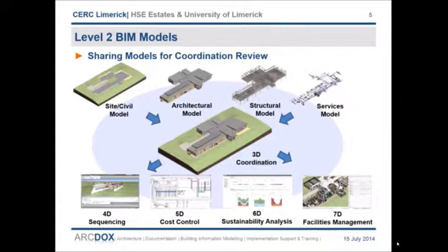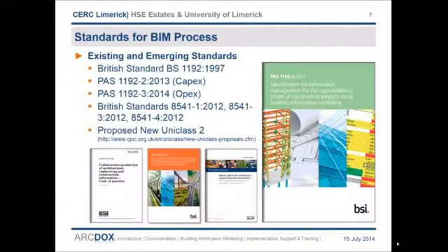The project team are encouraged to make as much use of BIM as they have the capability to do, but as a minimum the client and design team are looking for 4D sequencing, programming information and 7D incorporation of all asset information required for facilities management. Unfortunately, the benefits of the BIM process will not be realised unless there is a commitment from all participants to contribute to the process. And for that there needs to be a clearly defined standard and managed strategy. That requires every participant to adhere to when making their contribution to the project.